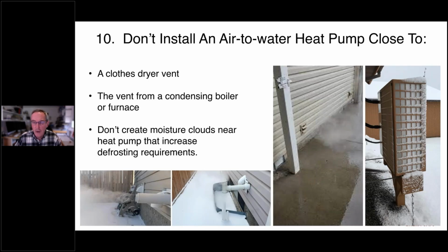So here's a coil on an air to water heat pump over on the far right there. And you can see that coil's completely frosted up. That unit is about to go into a defrost. And we want to minimize defrost because defrost is essentially scavenging heat from inside the building and sending it outside to melt that frost off. So the less defrost cycles we can go through, the better.